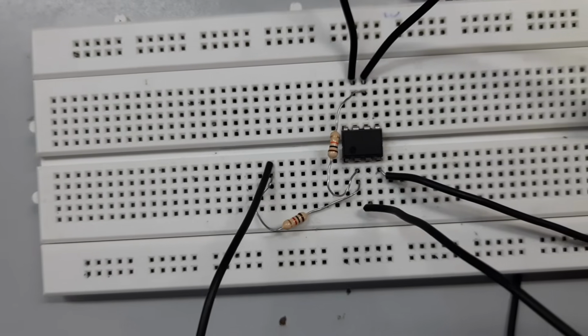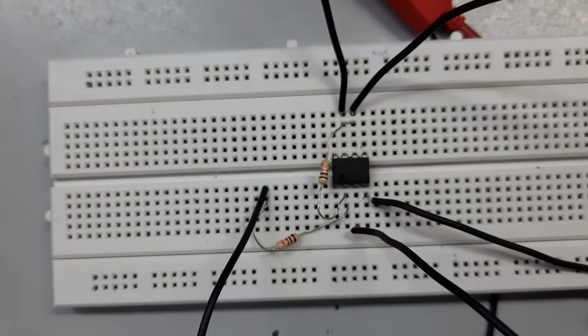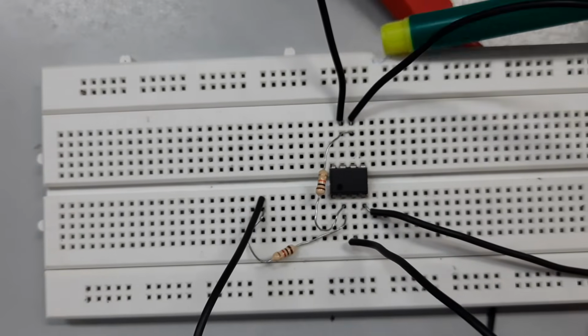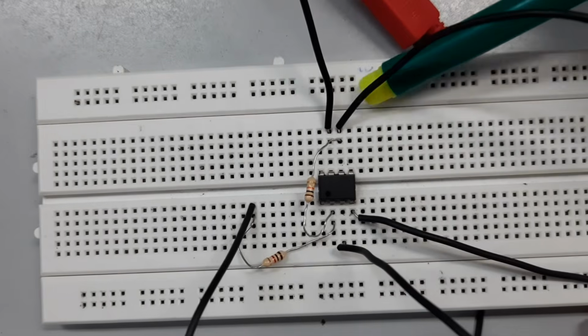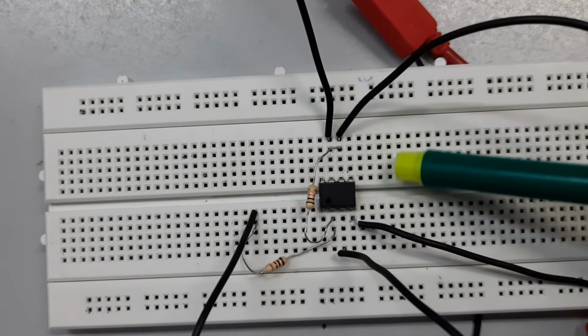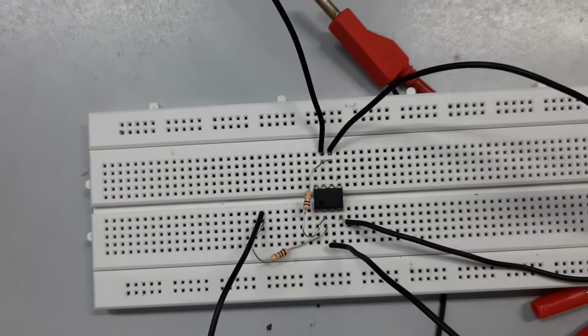So this breadboard is divided into two sections. One is horizontal section and another one is vertical section, right? So the outer ones, this one and this one, are horizontally short circuited, and this port, they are vertically short circuited. Means what? If you connect here or if you connect here, they are in the same form, but here the things will be in the horizontal form.